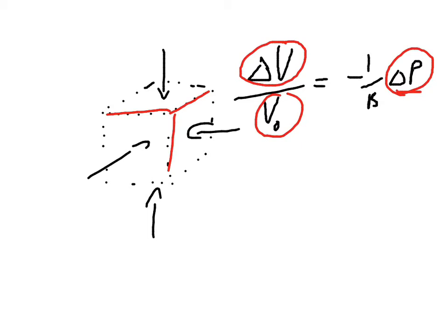Looking at slide 13, we then move on to fracture. So obviously if you're designing something, you want to pick a material that's not going to break. If you have a stress in that material that's bigger than it can tolerate, then it's just going to fracture, it's going to break. And it recommends here that when designing something, try to keep the anticipated stresses between 1/3 and 1/10 of the ultimate strength of the material.